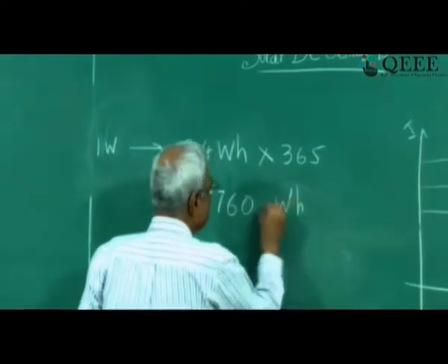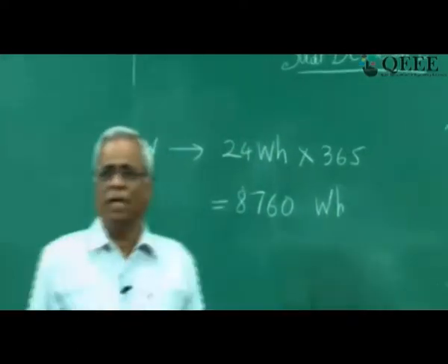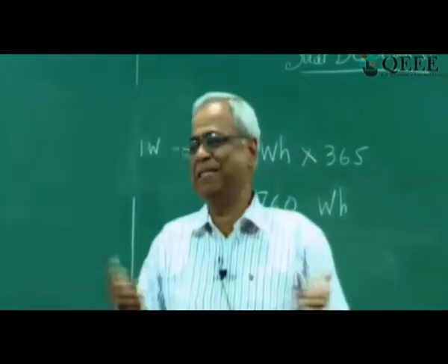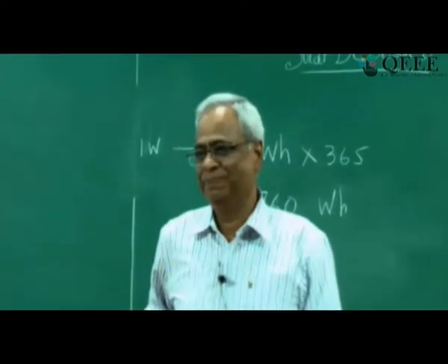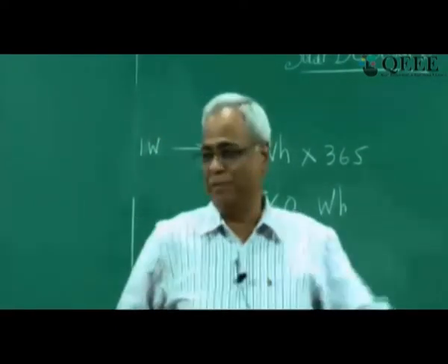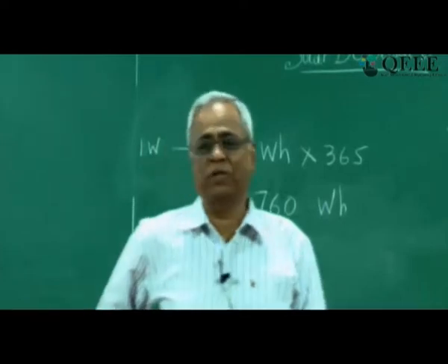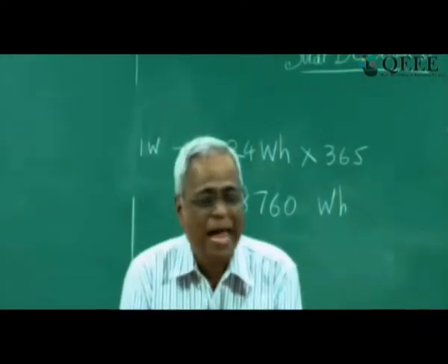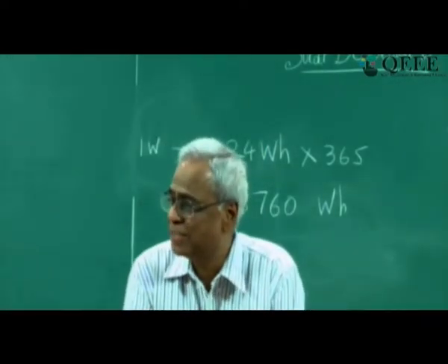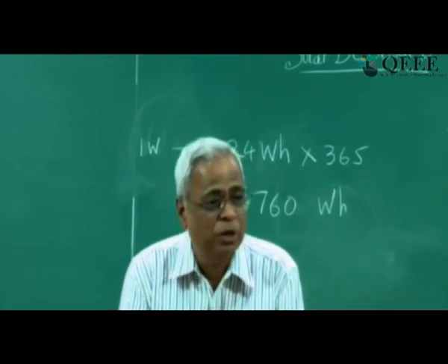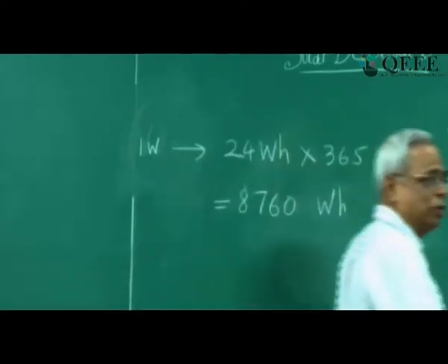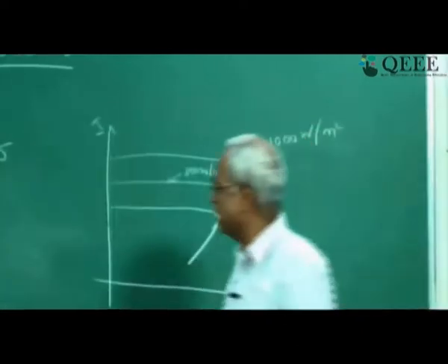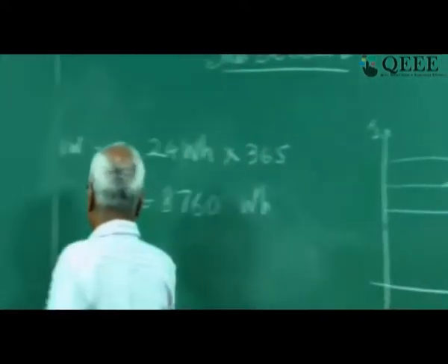watt hour. Now this would have been there if 24 hours of peak sunlight was available with no clouds ever. Now of course, first of all, sunlight is not available for more than 8, 10, 11 hours. Maybe 8 hours. You divide it by 3, 1/3 of it goes away anyway. So if you divide it by 3, in 8 hours